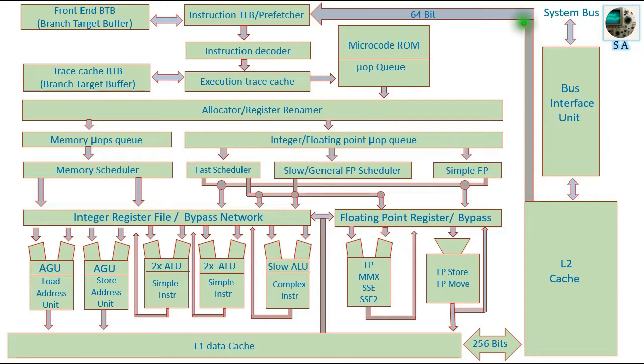Another good fact in this architecture: the already decoded instructions, or micro operations, from the decoders will all be stored in write sequence in the trace cache. This is considered the level 1 instruction cache. The micro operations will now be executed from the trace cache sequentially. This step, of course, boosts the performance of the decoding process and eliminates the bottleneck of needing instructions to be decoded one by one every time.